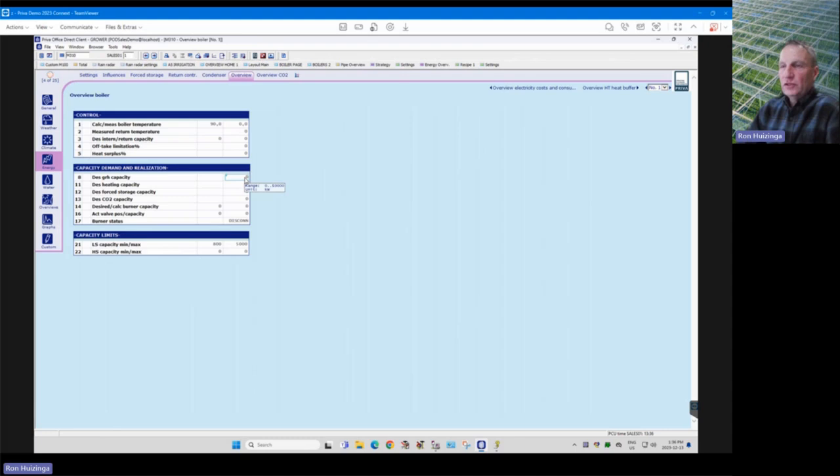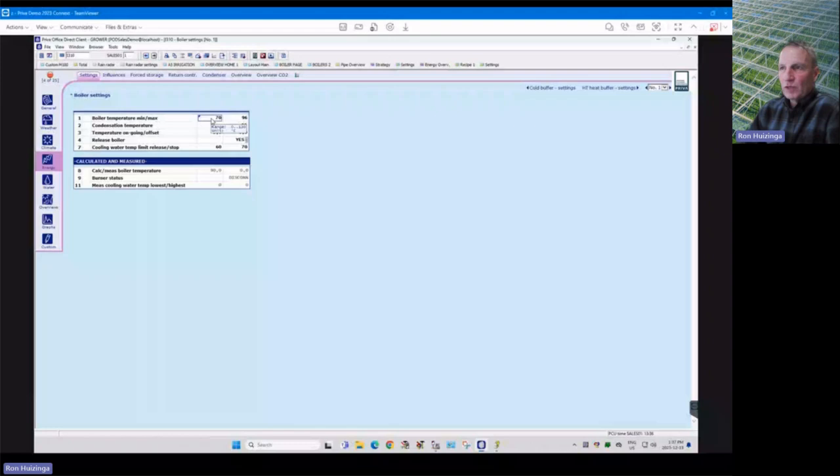So this is the boiler can start up for greenhouse capacity, which we don't want typically. It starts at CO2. That's typically what we want. And if we have a buffer tank, we have the desired heating capacity. So basically, like I was saying at night, if the temperature in that boiler drops below 70, then it says I'm going to need to kick on.